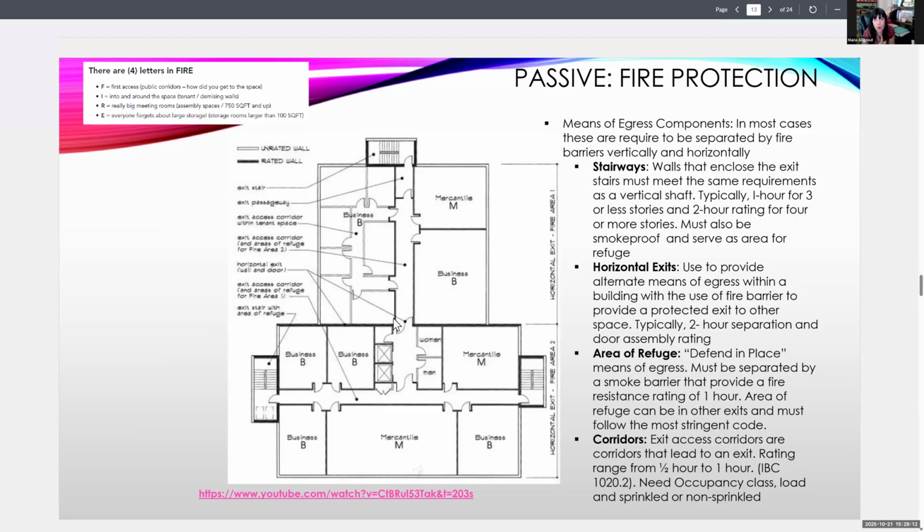If the wall is rated, all assemblies on that wall, windows, doors, all have to be rated. It's the rule. Okay. So you see that these are rated. Exit access corridors and area of refuge and fire too. So this also is another section, a different building here. Okay, that also has to be rated.